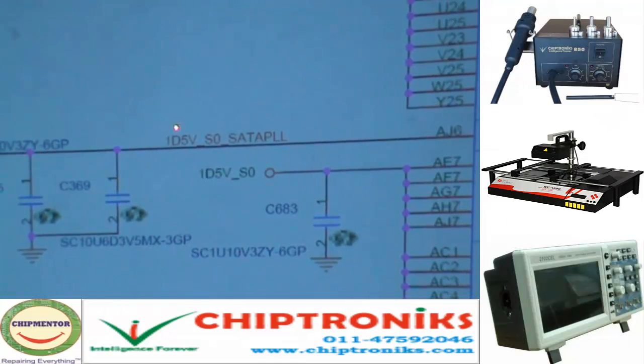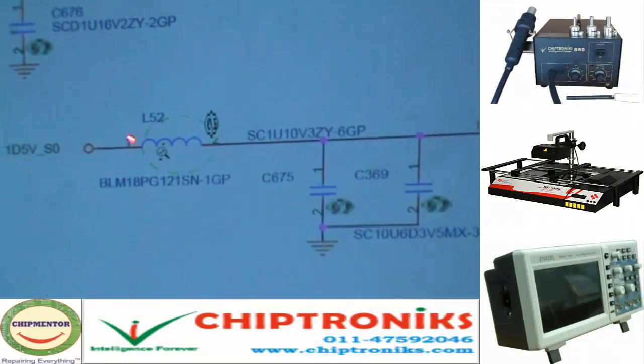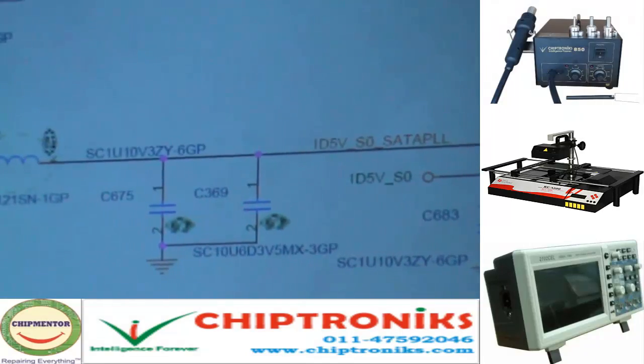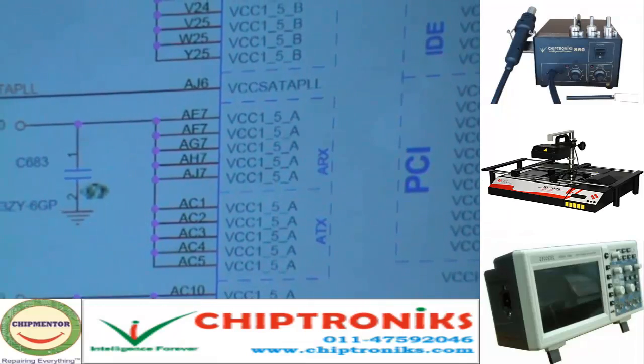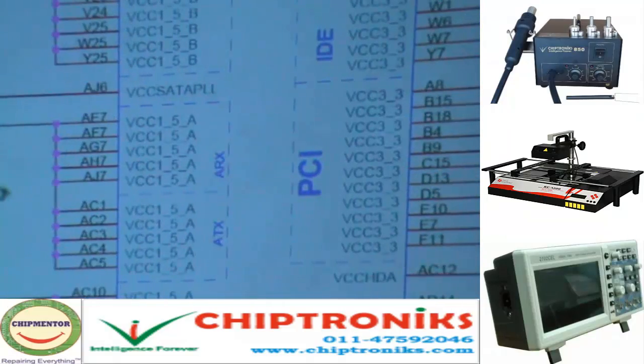First we have to check whether the SATA controller in the ICH is getting this supply or not. Here we can check 1.5 volt across this inductor. Coil, we also call it coil. This is generally an inductor.